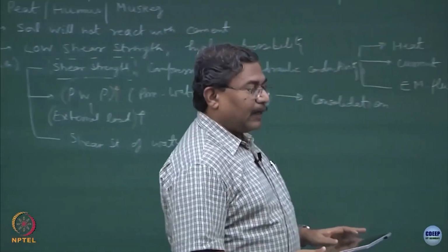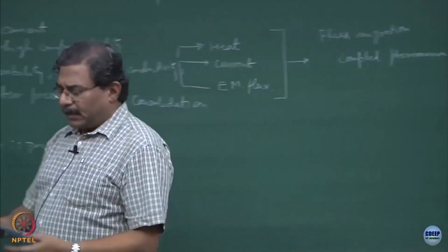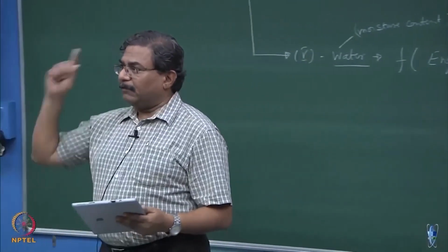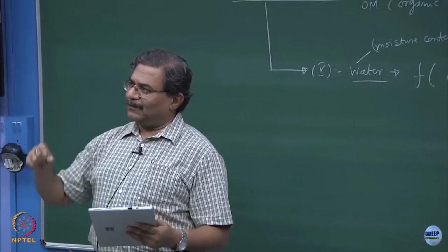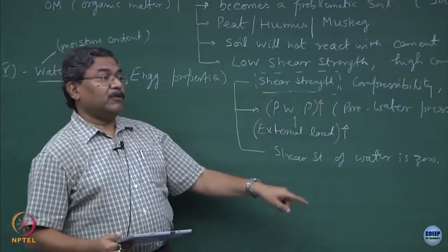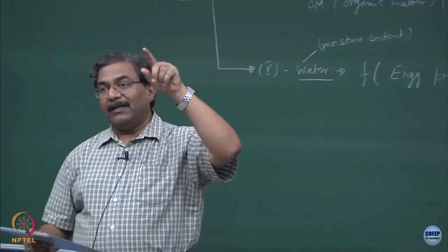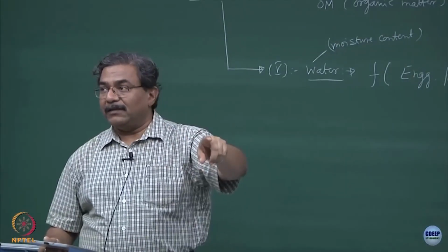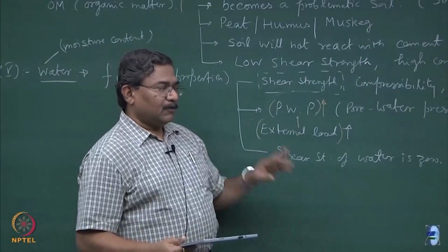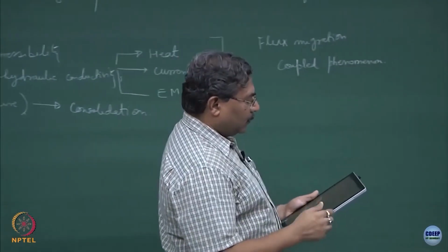You are on a beach and it is dry sand, and if I ask you to run, you can't run. But suppose the sand becomes wet, and you can drive a car on it also. Next time when you go to Juhu Beach, please try this, then only you learn soil mechanics. So, water also reinforces the material. It acts as reinforcement, like the rebars and steel you use in concrete. The more water present because of capillary action gives more shear strength. So, water is the main thing, and we have to study in quite some detail how it has to be modeled.